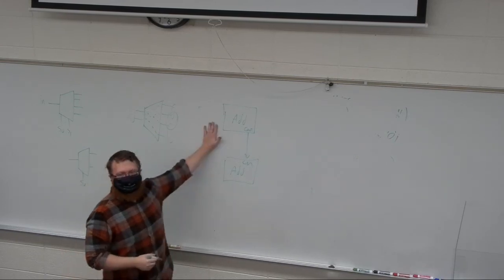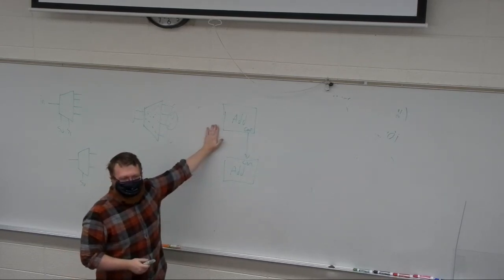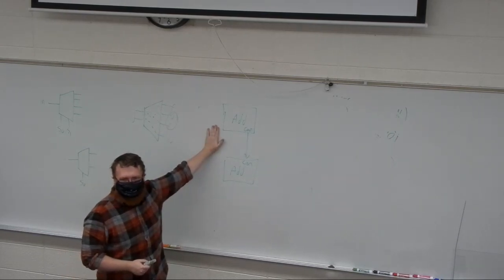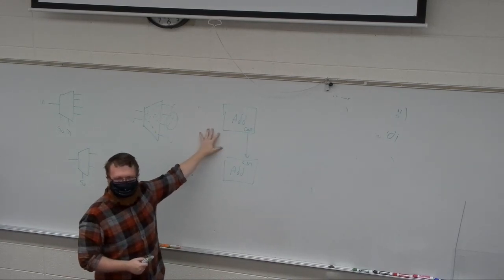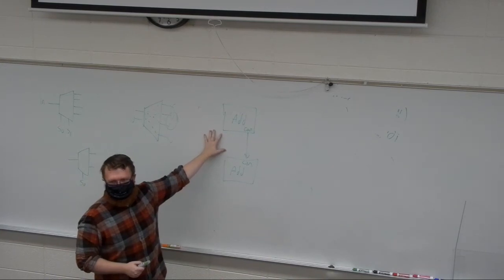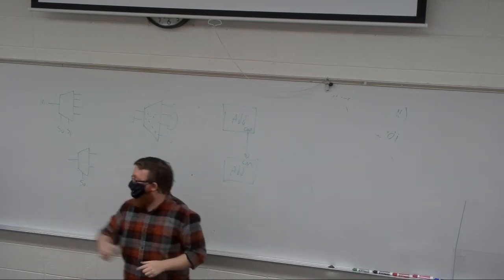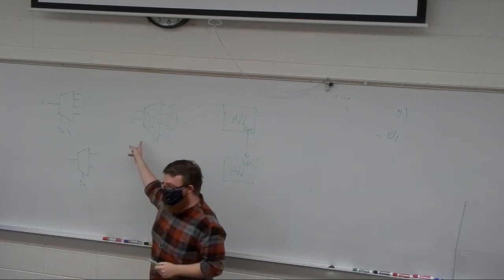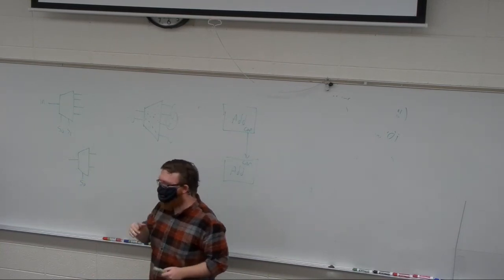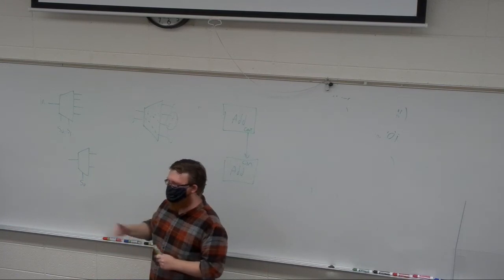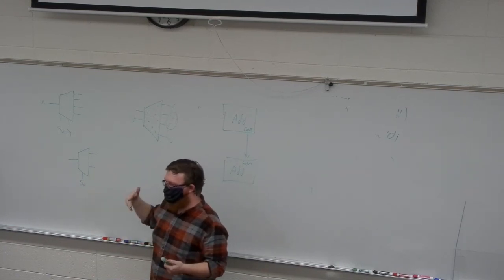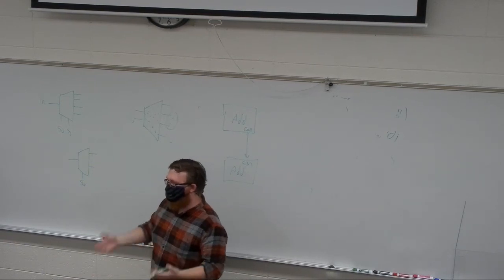Drawing block diagrams is really a good way to start a lab or a project, because it starts making you think about how things are connected together and how you might build them. If you're ever having struggles with something like the mux, start drawing muxes. If you're asked to build something using 1 to 2 demultiplexers, start by drawing a 1 to 2 multiplexer, drawing the connections that you think it should have.